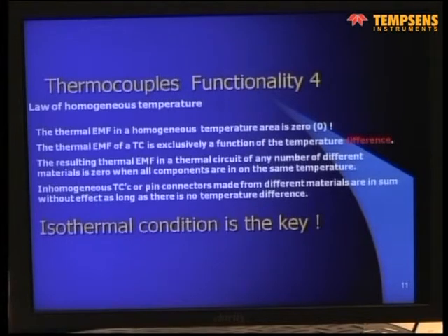Practically, we have to live day by day with different temperatures. Yes, this is our normal working day. We always deal with different temperatures. In no case do the input terminals of your transmitter have the same temperature as the wire between. In no case. That's life. So only under theoretical thermal conditions do you have no effects. But our daily work is to fight against such effects day by day when we use thermocouples. And as I explained before, resistance thermometers are not always the solution.